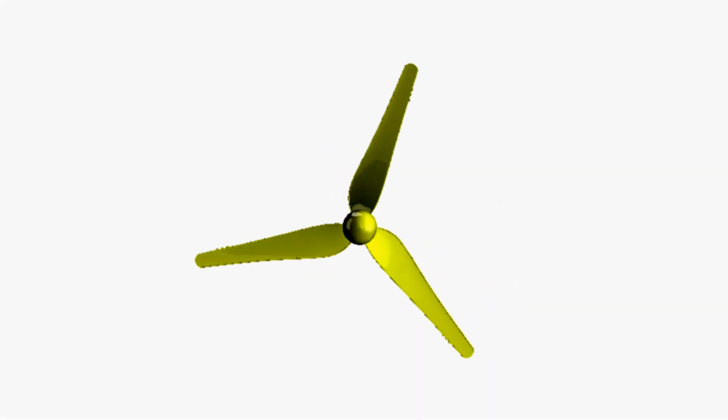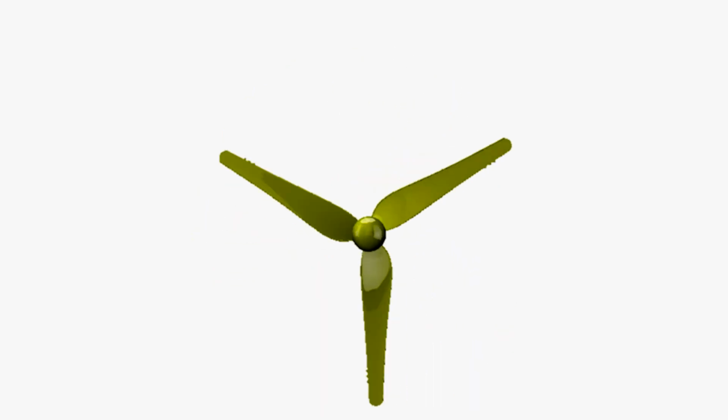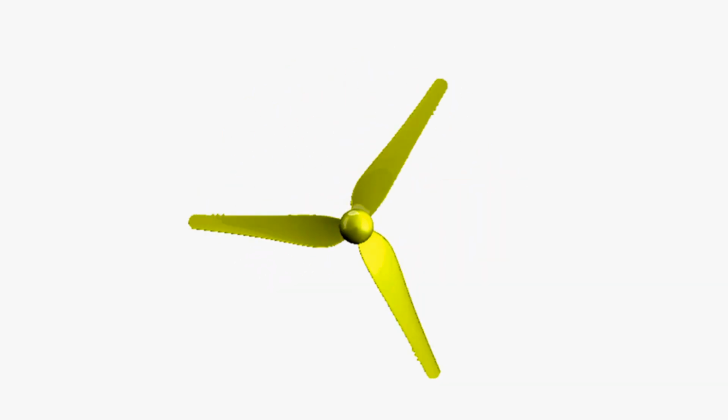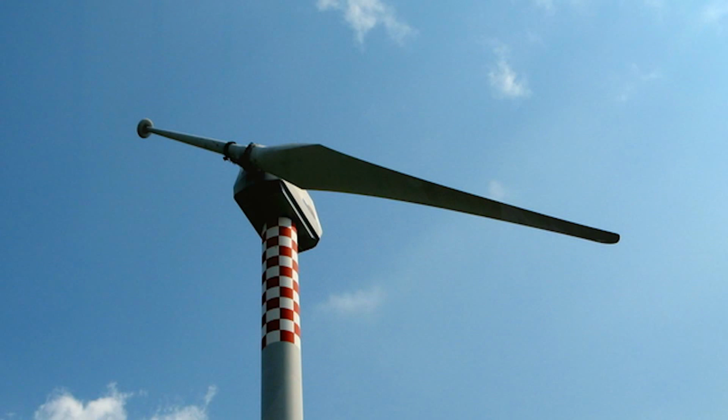Although using 2 blades will save on weight, we chose to go ahead with a design of 3 blades as it is more efficient than a 2-blade design of the same weight. A single blade design was not considered due to the complexity of designing a counterweight and the dangers of having an unbalanced wind turbine. Selecting the right aerofoil for the cross-section of our blade is next.